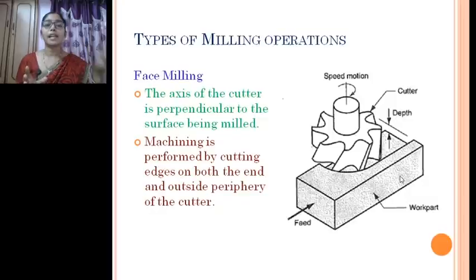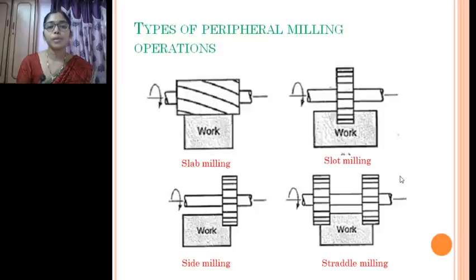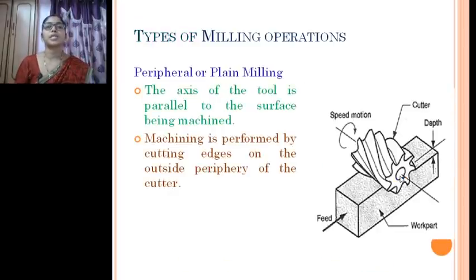Whereas in a lathe machine tool, even though you can hold a square or rectangular cross-section workpiece, the output obtained is of a circular cross-section. That is the main reason we go for milling operation, where we use multiple cutting edges, a milling cutter, to do the operation. Right. So the two types of milling operations are peripheral milling and face milling operation.